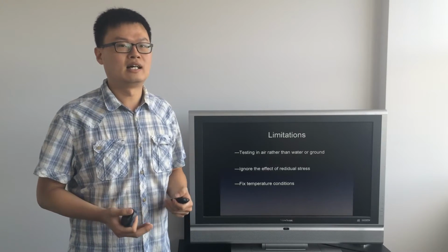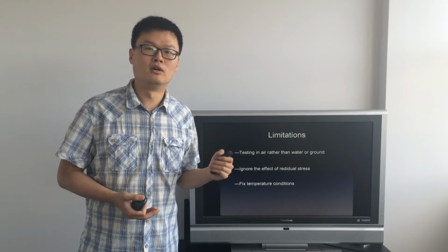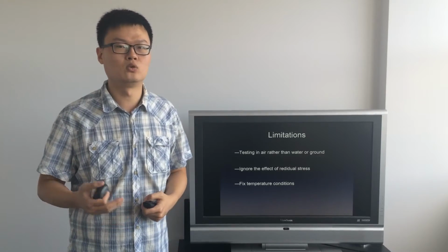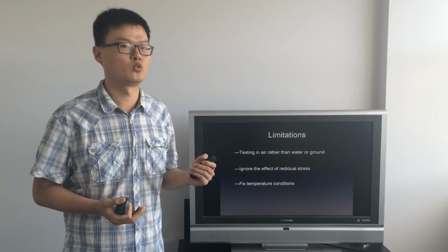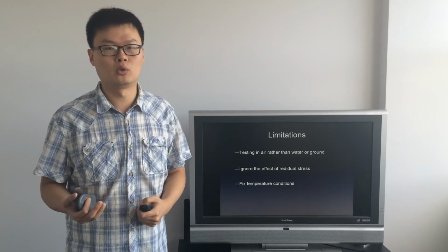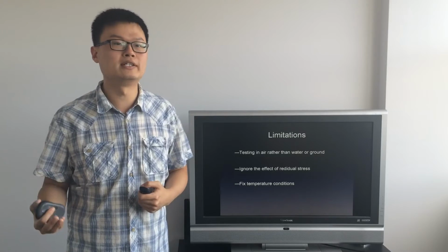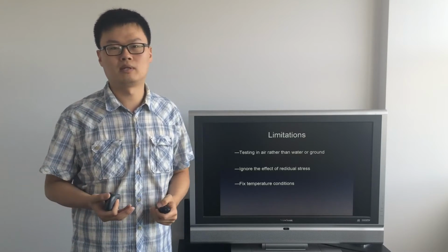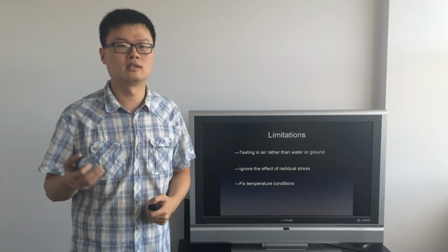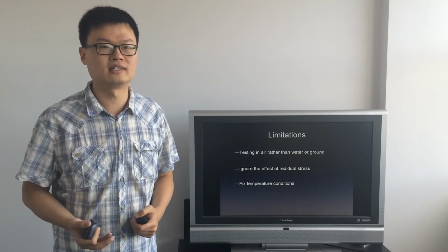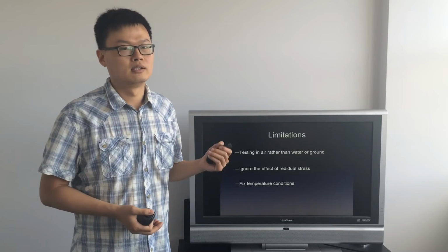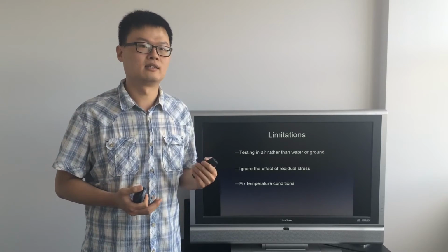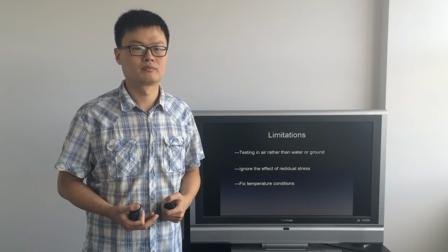In fact, there are a number of limitations in the research design. Firstly, both tensile tests were conducted in direct contact with air. However, the realistic situation in the transportation of gas and oil is that almost all pipes work underground or in water rather than in direct contact with air. Therefore, the results of the tensile testing could not reflect the realistic situation.